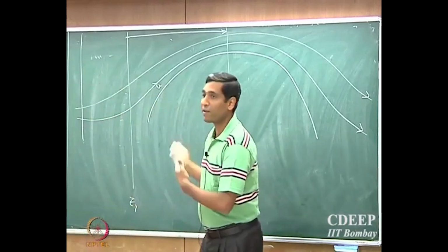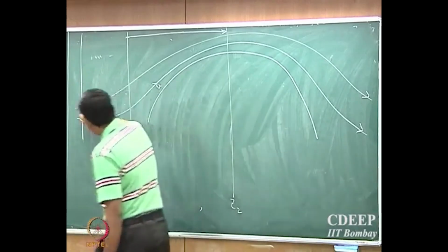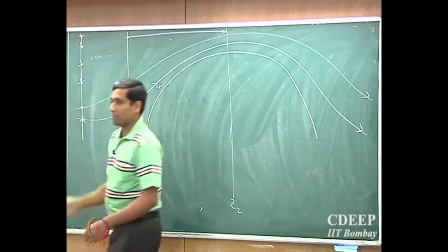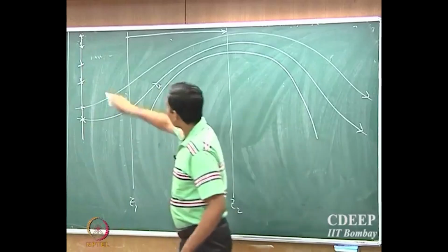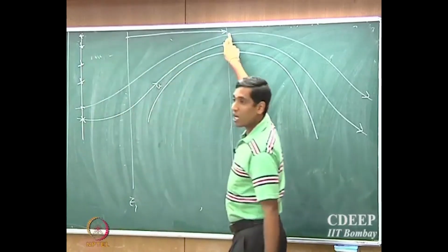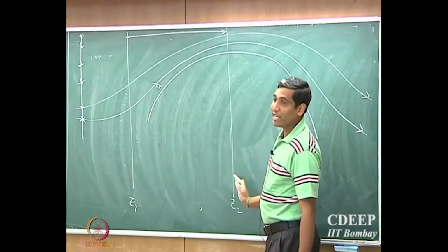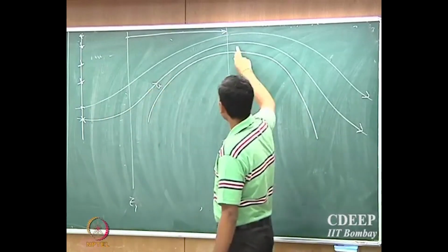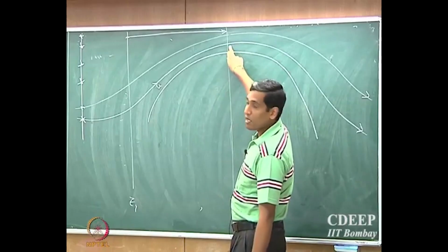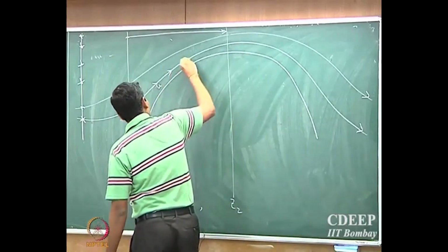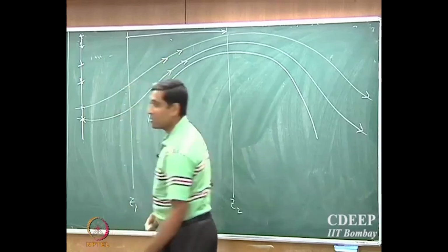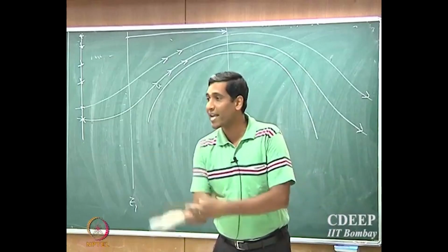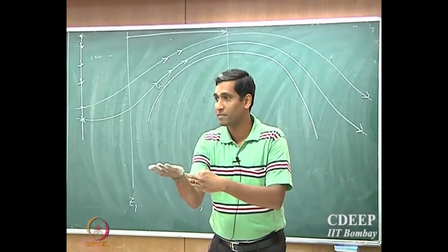So, if you look very far away upstream, all of these particles would have actually started at the same time. So, the distance that the fluid stream well above covers in order to reach the same plane is much smaller than these fluid particles that have to reach this location. Therefore, the fluid particles which are close to the cylinder, or which are experiencing the presence of the cylinder, have to accelerate in order to catch up.